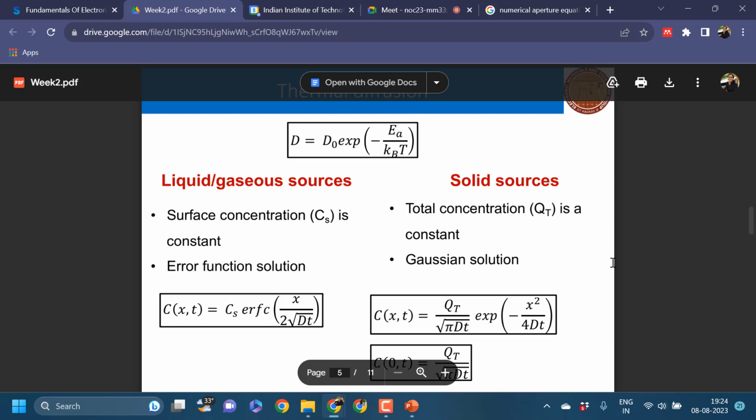So F1 is basically the oxidizing species that has to be transported from bulk to oxide layer. F2 means diffusion through the oxide layer, and F3 is the reaction with Si to form the new SiO2. And the flux is due to the difference in concentration at the bulk and the source. So in F1 basically they have given an equation, right?